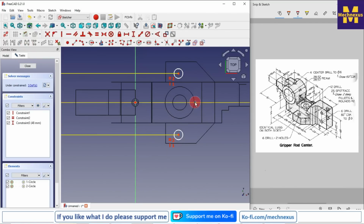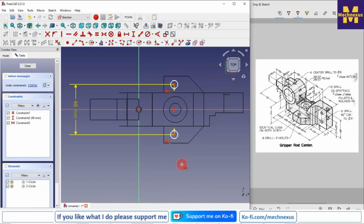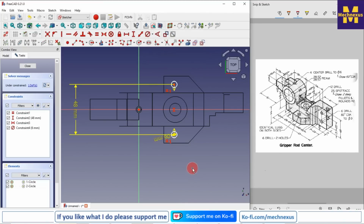So we have the mid axis, so we will use the symmetricity constraint. Select this point and the axis, and it is a 6 mm drill, so I will click on the circle and give the diameter of 6 mm.